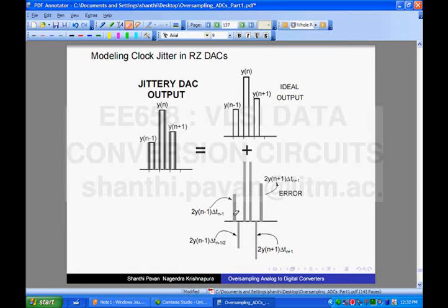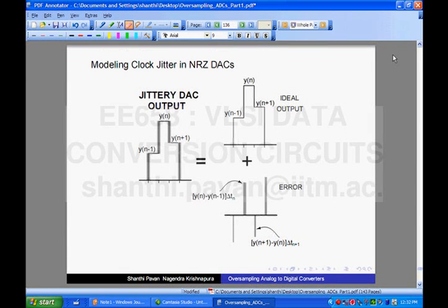So without thinking any further, can you tell me, in an oversampled situation, in a multi-bit D to A converter, how does the output waveform look? Let's say the input was like this. In a multi-bit converter, how do you think the output of the modulator will look? It will basically be jumping around the nominal, right? It takes only discrete levels, but the average must follow the input. So it will be some sequence straddling the input itself, and the jumps will be larger if.